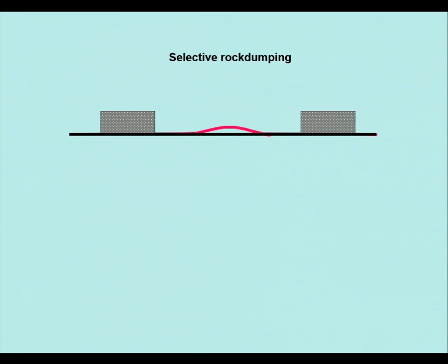So in other words, we can work out where it's going to buckle, and we'll put a mile of rock on it, and we'll go several miles, put another mile of rock. So we restrain it in those two rocks, and we can allow it to move and snake in between. So we're controlling the potential for buckling.